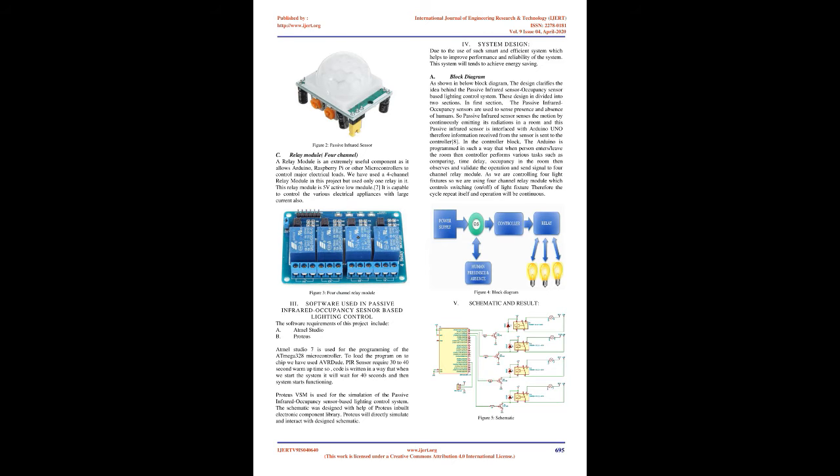The PIR sensor requires 30 to 40 seconds warm-up time, so the code is written in a way that when we start the system it will wait for 40 seconds and then the system starts functioning. Proteus VSM is used for the simulation of the passive infrared occupancy sensor-based lighting control system. The schematic was designed with the help of the Proteus inbuilt electronic component library. Proteus will directly simulate and interact with the design schematic.